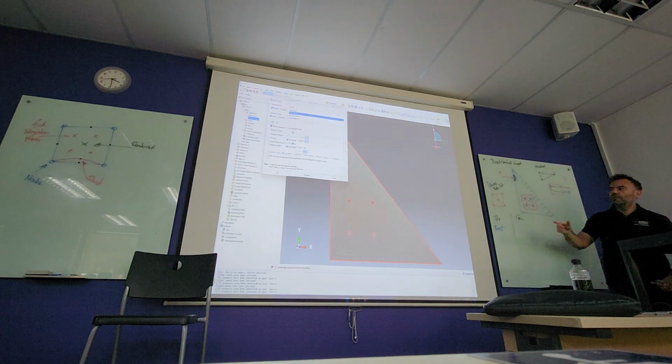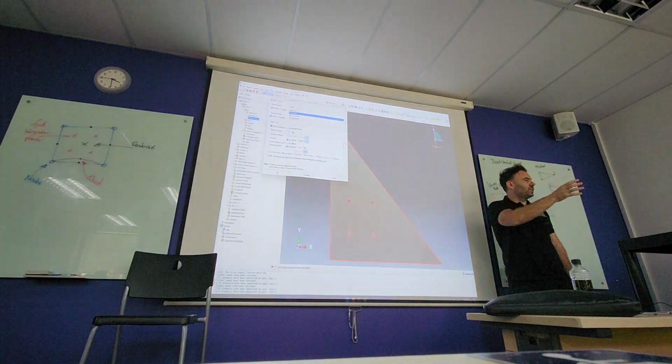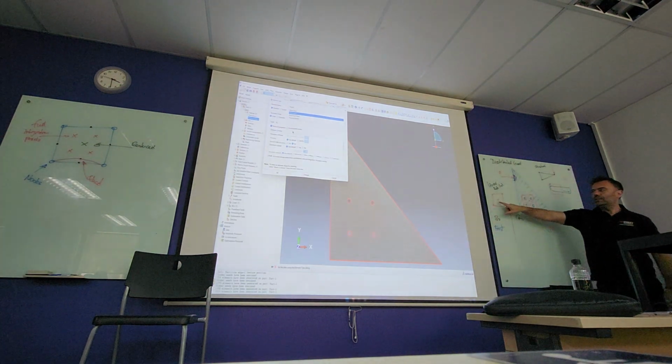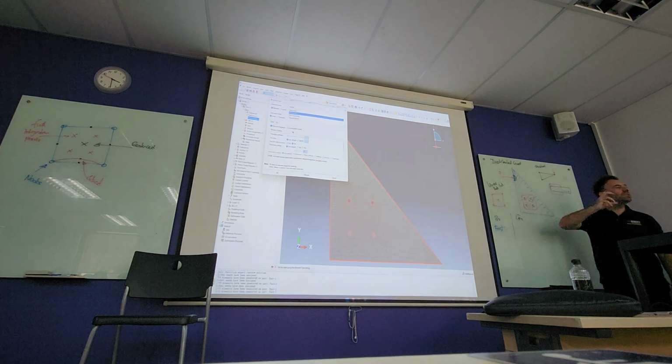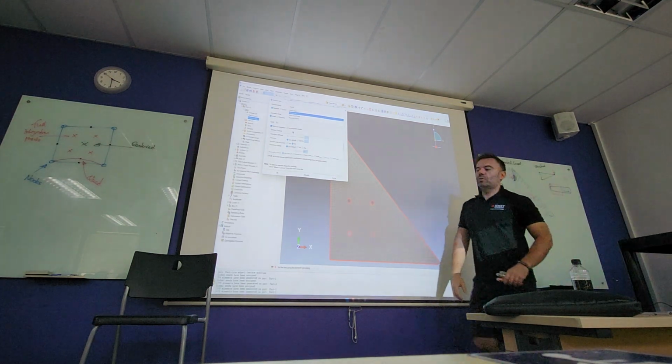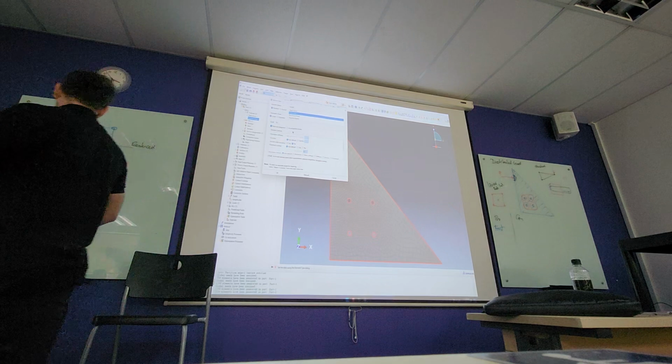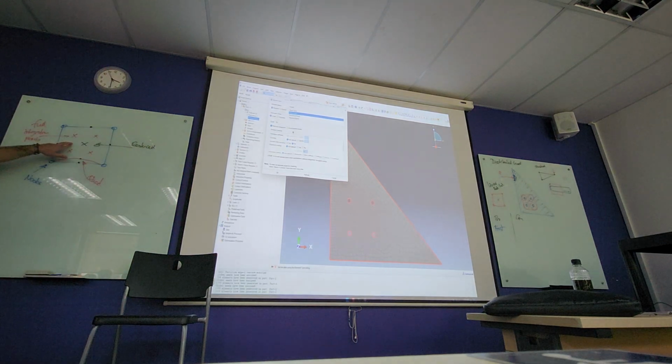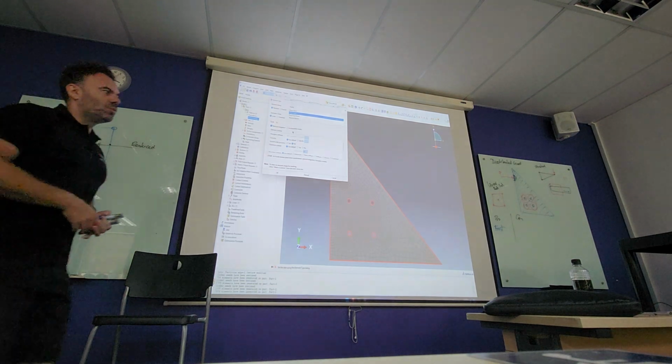So remember those matrices that we talked about, yeah? It's got one integration point, basically where the stresses are calculated, compared to 4. So at least, but it's more than that, at least with reduced integration it is 4 times quicker. So that's good. What's bad about it?